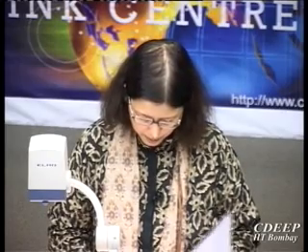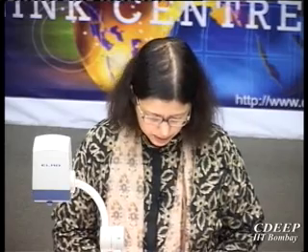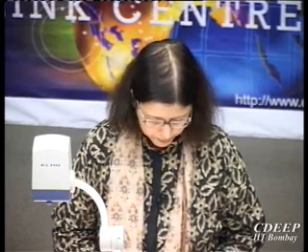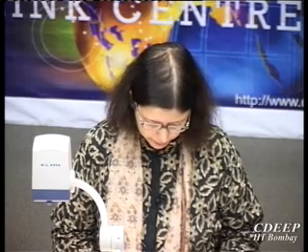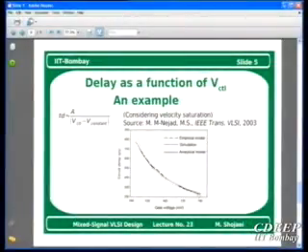Okay, therefore, now we have 2-3 examples. So the DLL loop will be almost single pole if we use a single capacitor at the output. By the way, we don't need to use RC as we discussed last time, because the DLL loop was stable, therefore we don't need to use RC. Therefore, it makes it first order, and then the design parameters will essentially be just time constant and loop bandwidth.